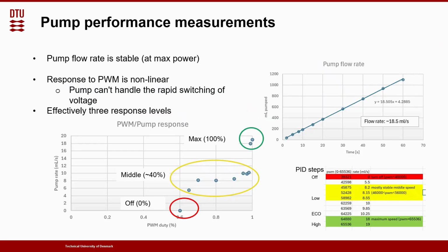We measured the pump performance and found it's stable at max power but does not respond linearly to PWM input from the board, which makes sense considering its construction. Instead, it exhibits 3 response levels: max power, a single mostly stable middle level, and off.